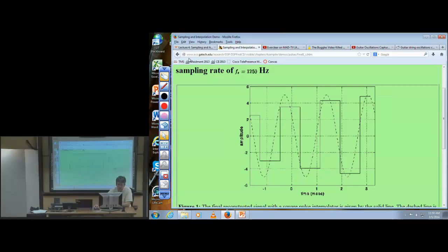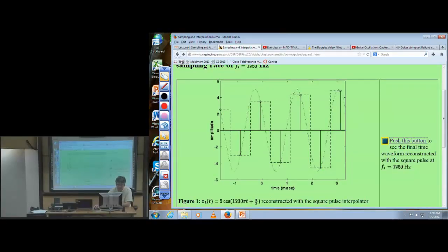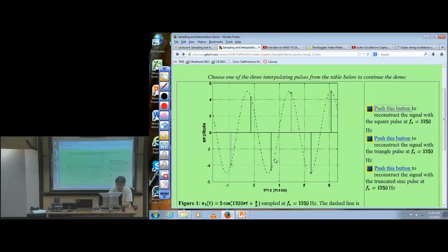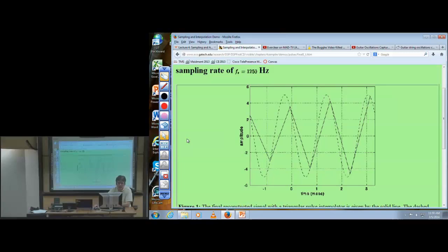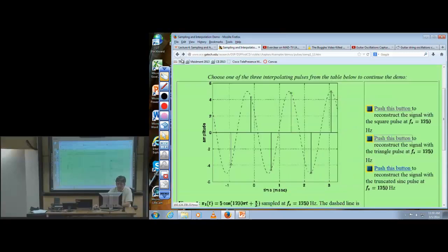That's not great looking. Now let's do linear interpolation, which is to take the samples that we have and just draw straight lines to connect them. A little better interpolation. Zero crossings are at the right frequency, but not the right location. Last, we do an ideal low-pass filter by filtering this discrete time signal with a truncated sinc in the time domain.